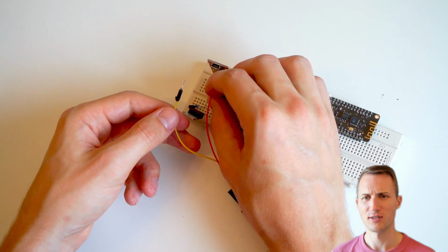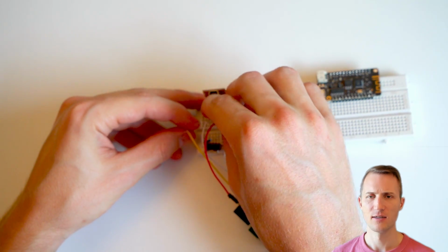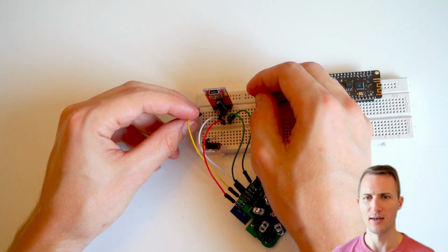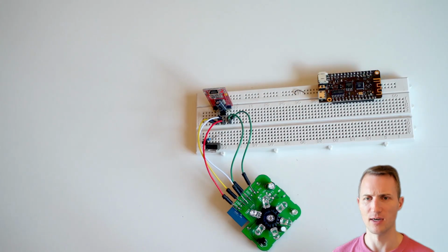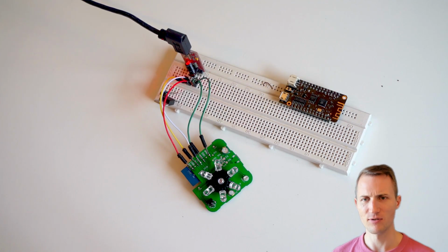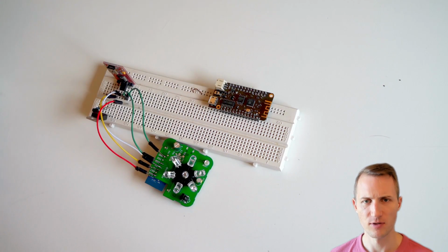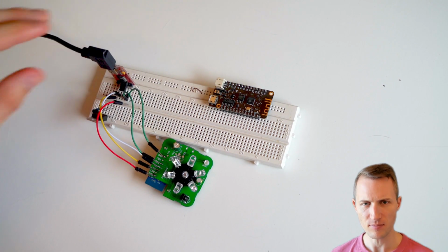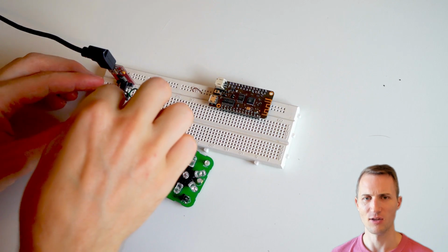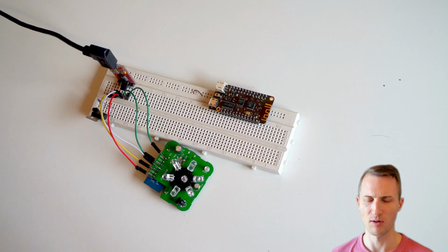And you might notice that there's a capacitor, a little cylinder, just near that programmer, or RS232 serial converter, and that capacitor sort of stuffed things up a little for me. It's needed for some chips because the ESP32 can have some big spikes of power consumption. In this case, I needed to remove it. In this case, I needed to connect the USB cable, let it power up, and then turn on or reconnect the power cable of the controller.